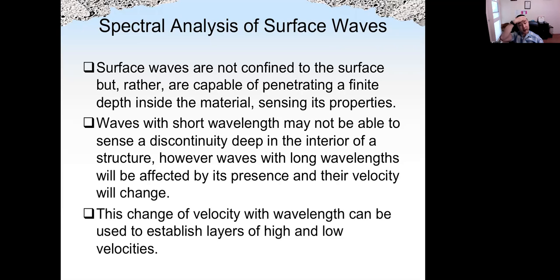But actually, surface waves are not only confined to the surface. They can penetrate to a certain depth depending on the frequency, so you can sense the properties at a certain depth beneath the concrete. For waves with shorter wavelengths, the energy dissipation will be faster, so you may not be able to sense discontinuities deep in the concrete because the wavelength is too short, but it's very accurate.